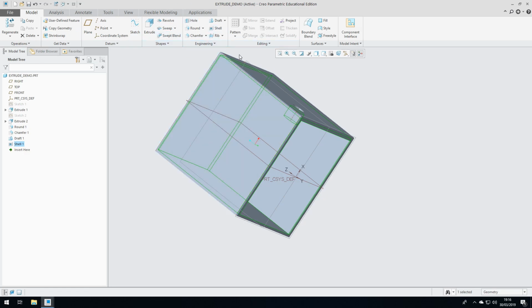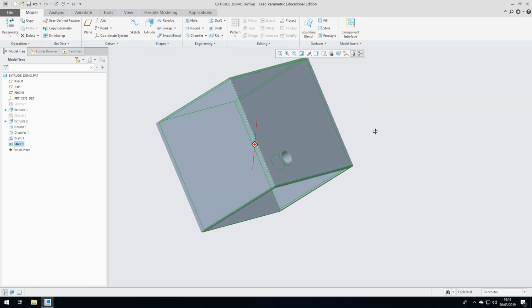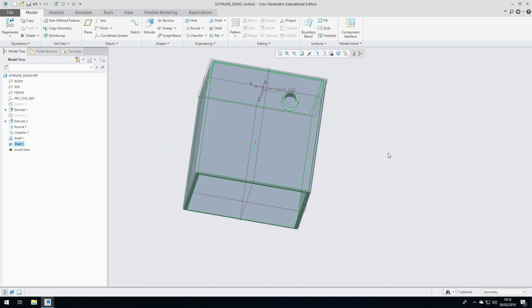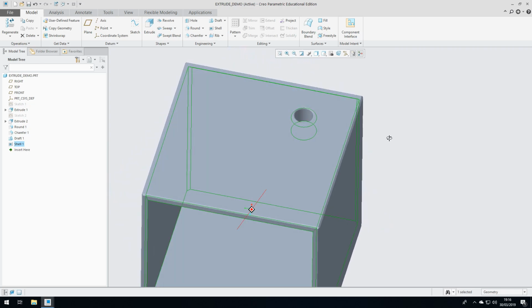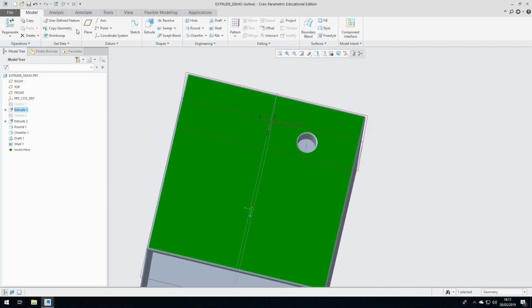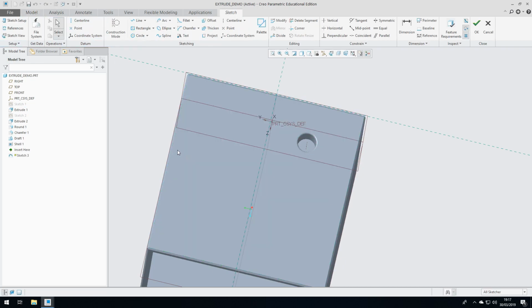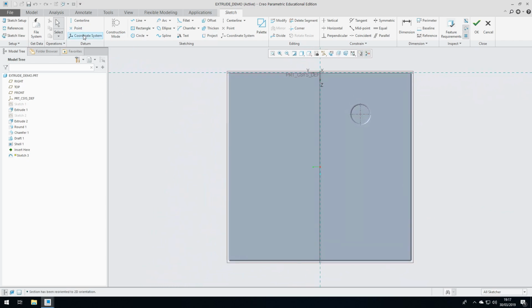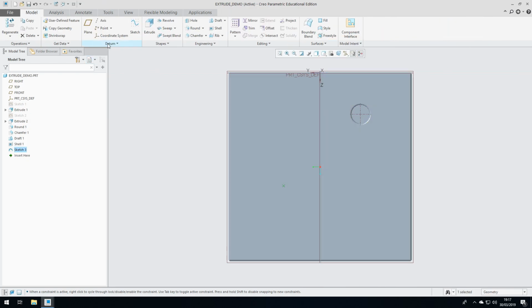Yeah, that's a lot of the engineering tools within this. It's a very simple sketch that I've done at the minute. So, another thing I will show you, generally for engineering common practice would not be to extrude a hole into a material, especially if you're going to have it tapped or a through hole. What you would generally do is sketch on the face. Add a point in where you want your hole, so for example there, and then set the dimensions. So if I make that 50 and that 150, if I knew I wanted a hole in that position due to the top surfaces, I would do that, and then I would use the hole function.